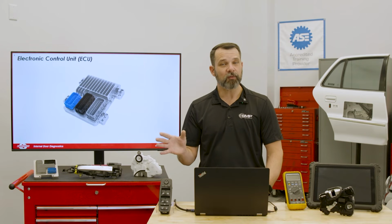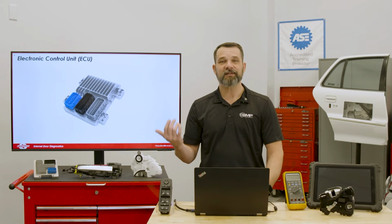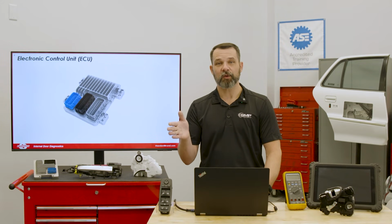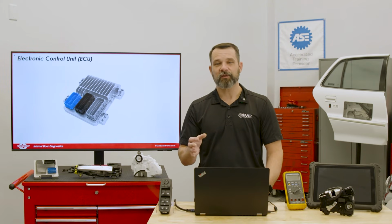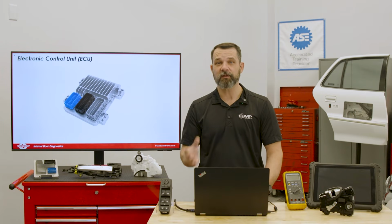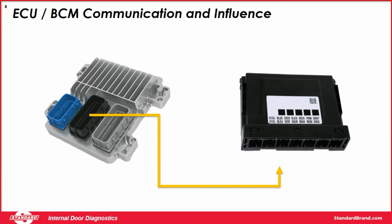And while that body control module is going to take care of things like the functions of the windows and the locks, that ECU is going to provide the vehicle's main operating context. So, things like the ignition state, the vehicle speed, the load, the charging system status, and even security authorization. In these modern vehicles, the ECU is not isolated. It's part of the network of modules that are constantly communicating. And these body functions, and especially certain body functions, will not activate unless the ECU gives the okay. And it's important to remember here too that the ECU shares data over the network to allow or restrict body functions.